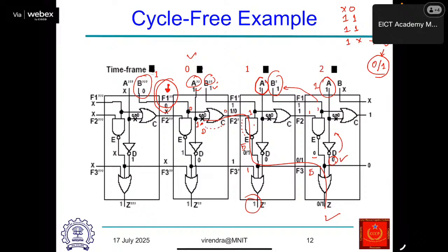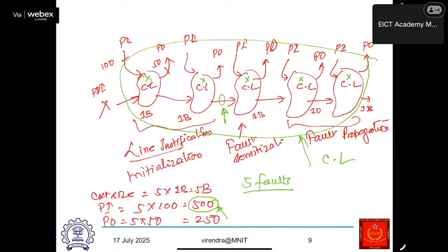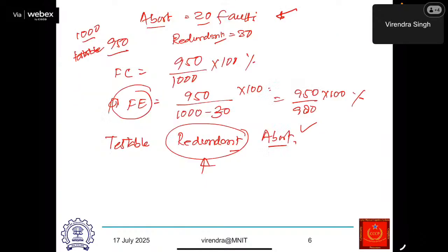The abort faults are like this, for example, I said that earlier as well. Say that I have a circuit and generate the test for that. Now let's say I target one particular fault and start to run my ATPG. And let's say that to generate the test for one particular fault, it takes 5 days, right?